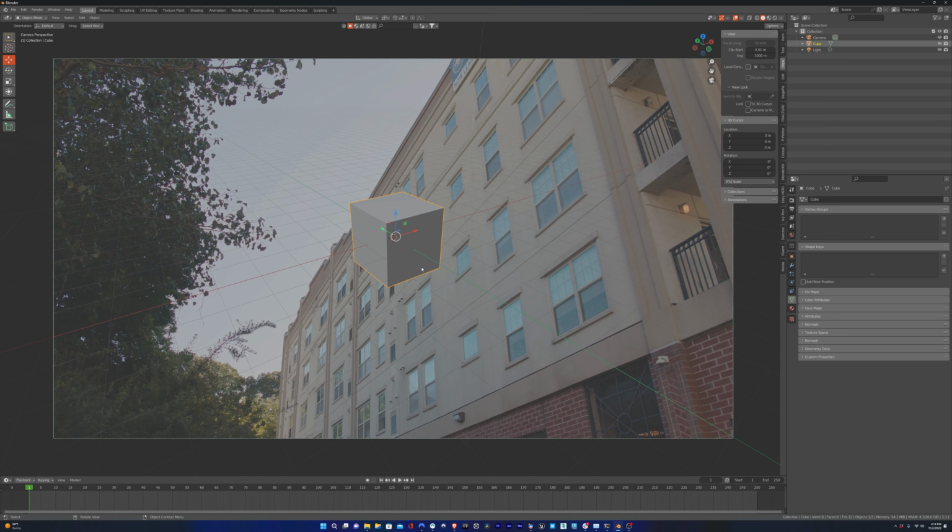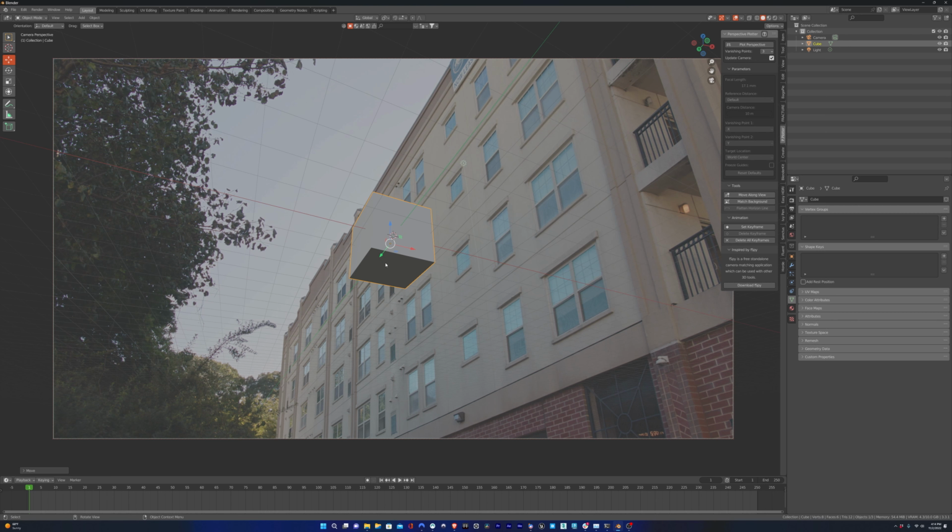I'm just going to enable this for now. Technically, we're looking at it sort of somewhere like this. This is not an exact match, but let's say this is a rough estimate. If our depth is y, then we need lines that match up to that axis. So that would be any of these frames in the windows, this section of the cement right here, this down here. All of that will work for our depth. And then for up and down, obviously, we can just take any of the edges of the windows. We can take the edge of the column here. And then for our x-axis, we can probably take this line here or a line over here. Just something that goes left and right.